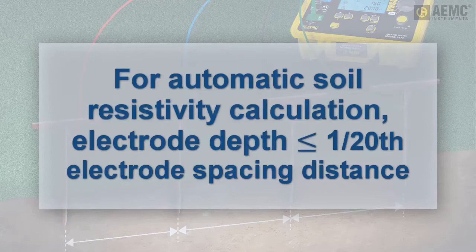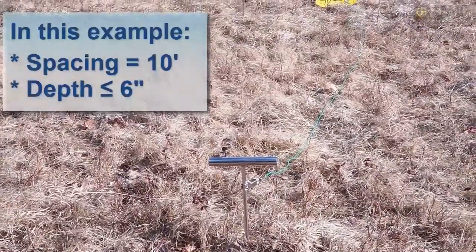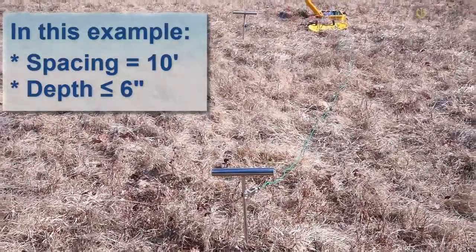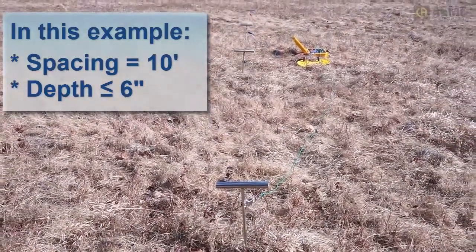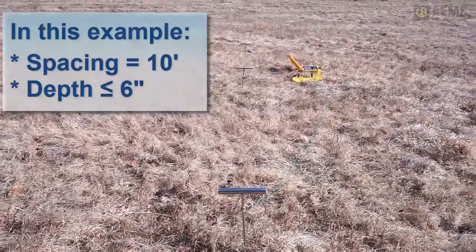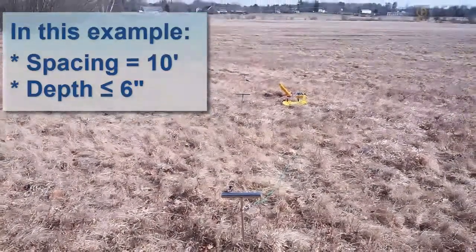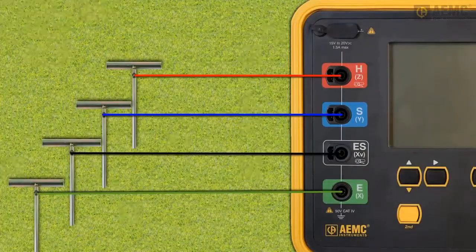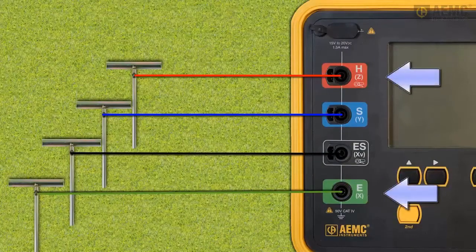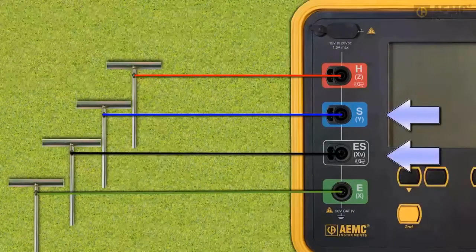So for our demonstration, we will place the electrodes 10 feet apart and no more than 6 inches deep. Other distances can be used as long as depth does not exceed 1/20th of the spacing. Note that when calculating the spacing to depth ratio, the spacing distance is the primary value. Determine the electrode spacing first, and then adjust the depth accordingly. The 2 outer electrodes are connected to the instrument's outer terminals, labeled H and E. The inner electrodes are connected to the inner terminals, labeled S and ES.